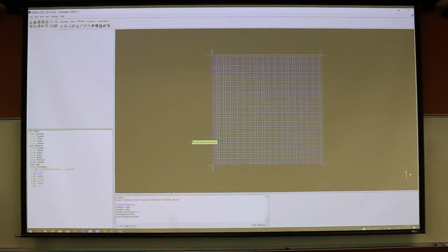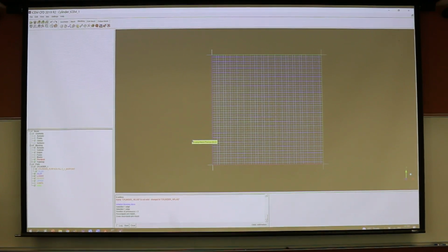Your mesh elements here could be of a good shape or a good skewness, but here this whole 90-degree will be very highly skewed elements. To overcome that, what we do is that we will merge these two sides. If you merge these two sides or these two edges, then you will have only one edge, and this is the mesh that we're going to create.